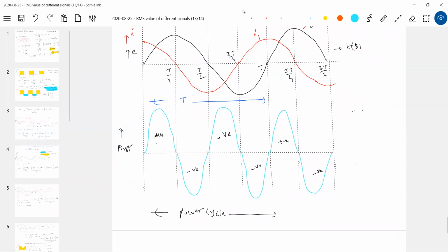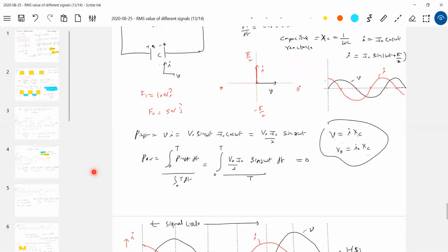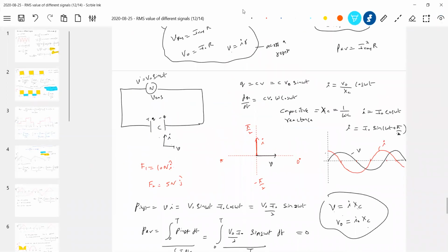So what is the capacitor now? What is the role of it? It will just make current lead the voltage by 90 degrees. So therefore that reactance is what we have brought in. Of all, this is very important. And how to apply Ohm's law across a capacitor? Not IR, I into XC. The drop across the capacitor should be like this.